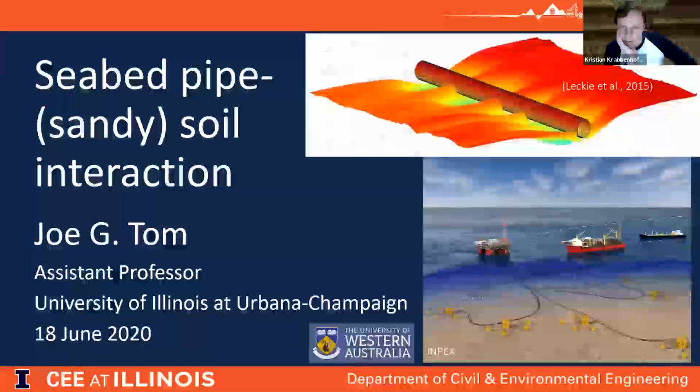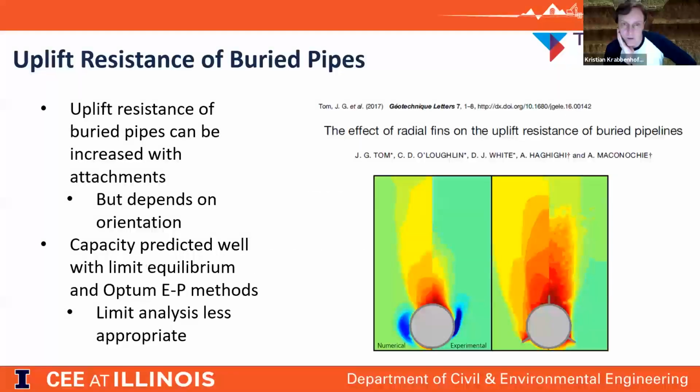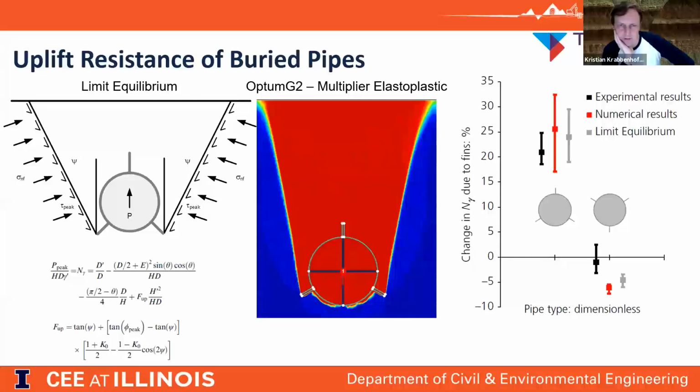And then for sands, this is another question. The friction angle might not be constant, right? These are all plane strain analyses, so it's the plane strain angle, I guess, that's the appropriate one, but it could still be stress level dependent. Is that something you have considered, or is it not relevant? You're outside the range of the confining stresses where the dependency is greatest. Of course, at very low confining stresses, you can have quite a bit of variation.